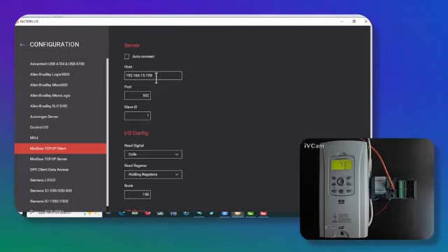Well, in the XG5000 software, we set the PLC's IP address to 192.168.15.100. Here, as you can see at the top, we need to provide the server details to the software. It says that the server you are going to connect to, you will read some information from it and write some information to it. What is its IP?